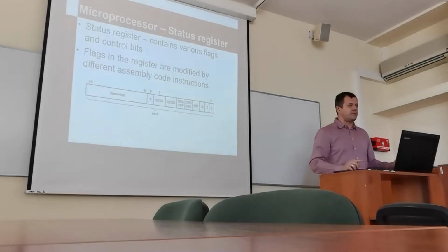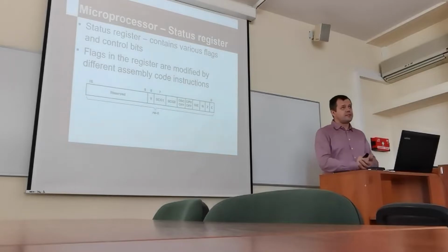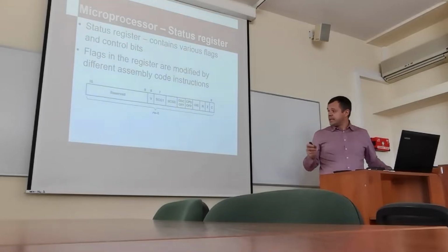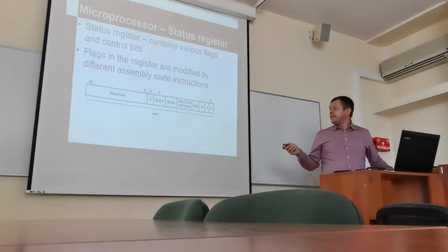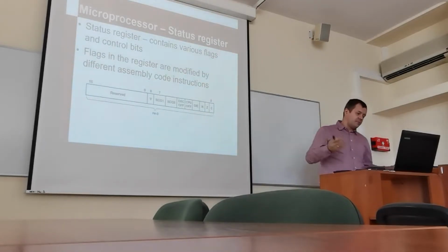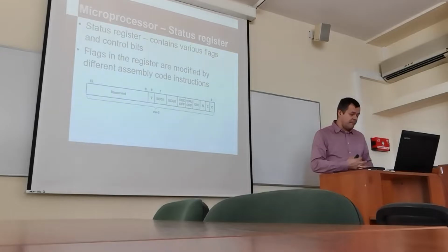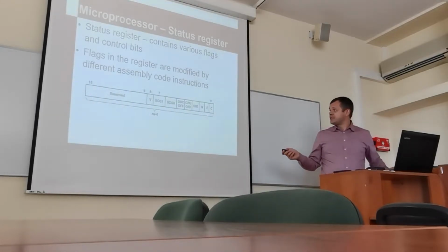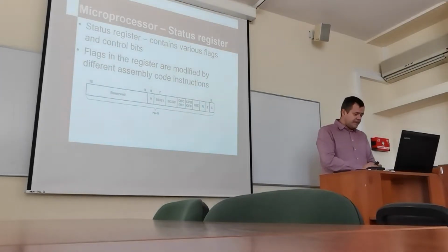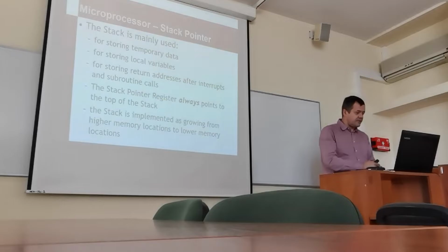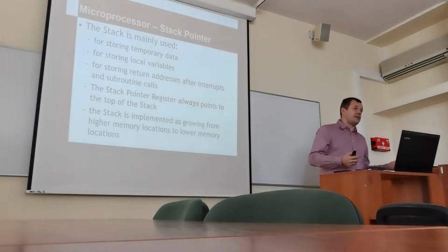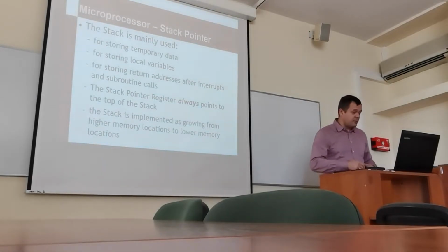Today, it's not necessary for a microcontroller to be, the status register doesn't need to include it, but almost always it includes flags like the interrupt flag or some power supply options. So here is oscillator off, CPU off, for example. Yet these are not a must-have. The must-have in status registers are the basic flags like N, Z, C, V, H, and sometimes some other status flag from the arithmetic logic unit. Next auxiliary element, not necessary, but always available, or almost always available.